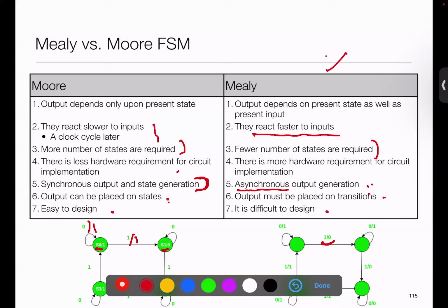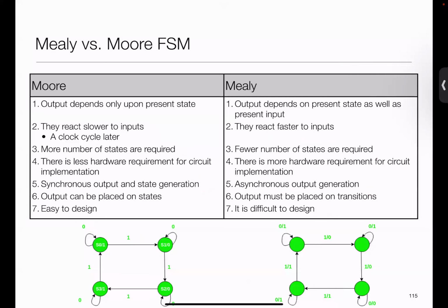Generally, I would say I frown on Mealy for hardware design. Mealy is perfectly okay if you are doing a software finite state machine. Finite state machines exist in software systems also, and Mealy is perfectly okay there. It has advantages, but Moore on the hardware side carries significant pluses on balance. So let's talk about how we can switch back and forth between them.